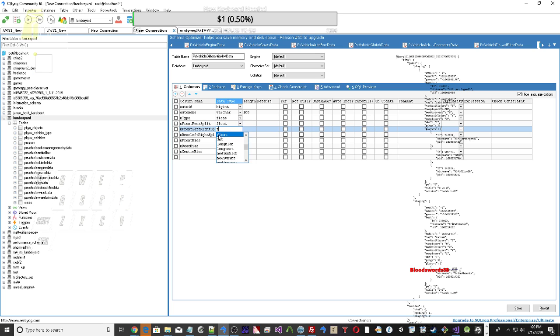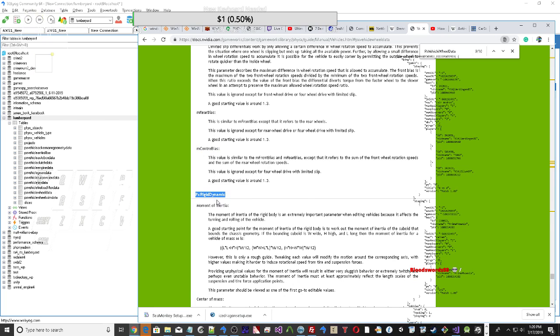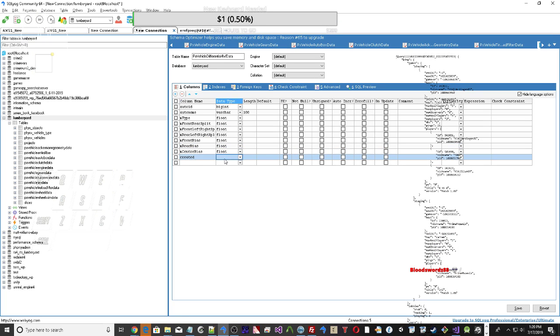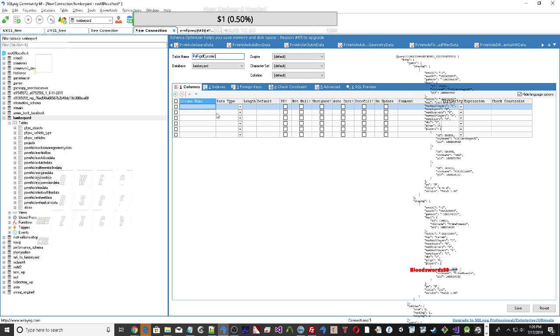As an illustration of the usage of these functions, Snippet Vehicle4W has the following initialization code. PxInitVehicleSDK(*gPhysics); PxVehicleSetBasisVectors(PxVec3(0,1,0), PxVec3(0,0,1)); PxVehicleSetUpdateMode(PxVehicleUpdateMode::eVELOCITY_CHANGE).